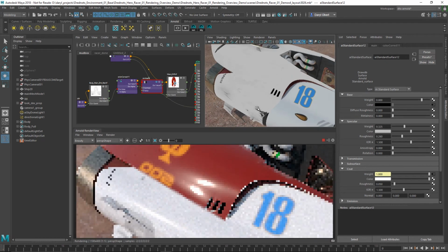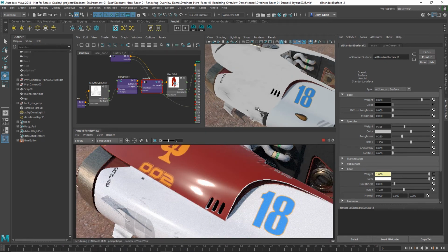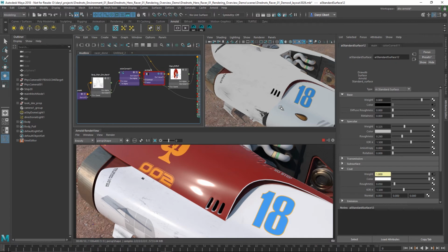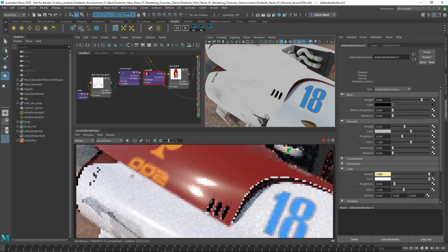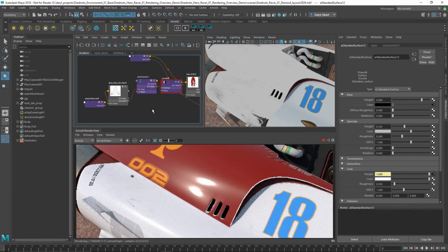And what we want to do is refine the overall roughness of this piece of geometry on that clear coat from a low value to a high value to get those scratches to show up a bit more. So you'll notice that 0.05 to 0.4 is sort of the range that we were using. So where there's dark areas, we want to have a very broad highlight, and where there's light areas, we want to have a very tight highlight.